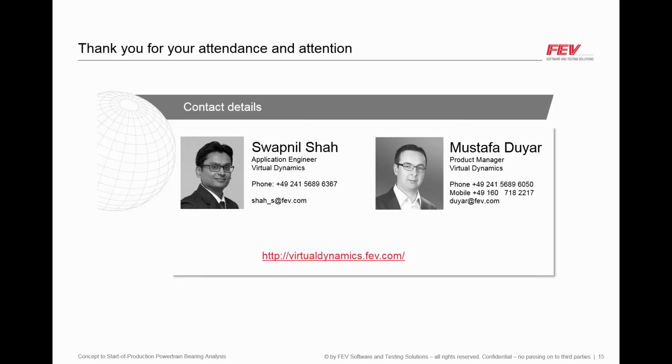Of course, the standard method where you can define the entire sprocket, the tooth and the tip radii with just a single radius, single arc, it's still available. The profile detail, the advanced profile, which I showed today in the demonstration, is an additional functionality. This profile, for example, becomes very important if you want to investigate the root stress in your sprocket.